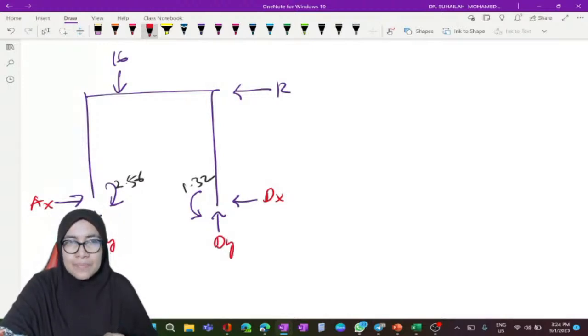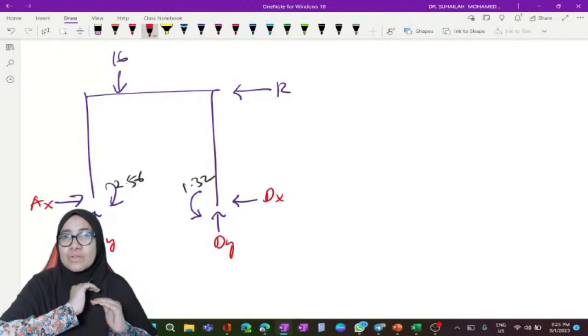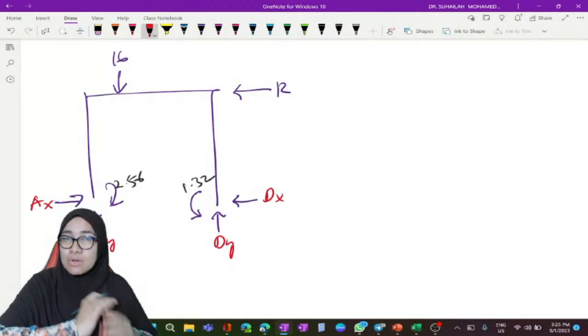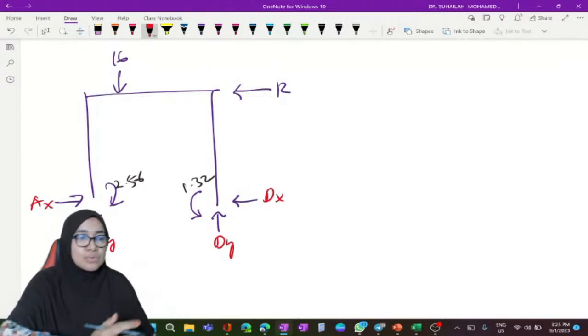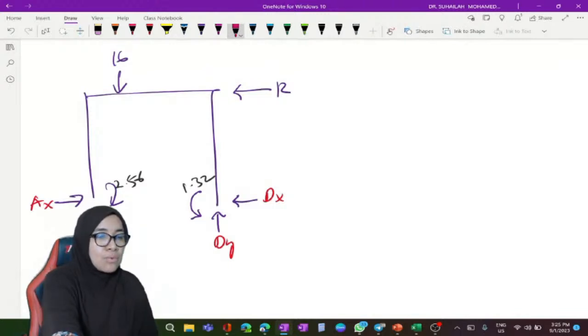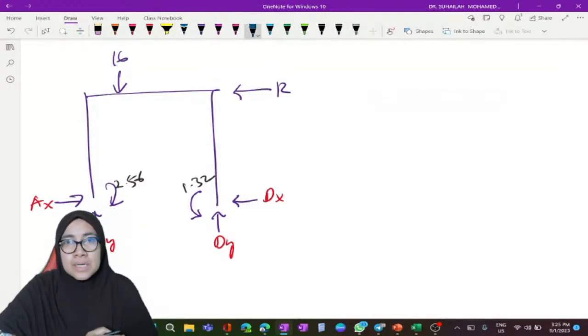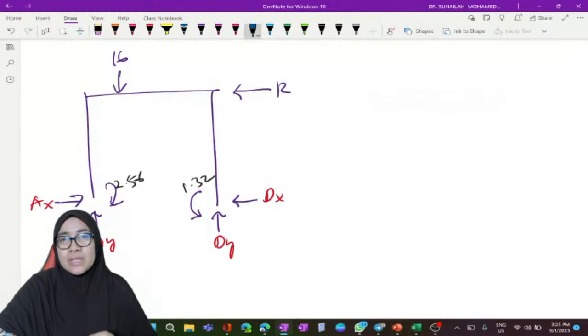Remember, at this level, we are analyzing this to determine the restraining force value. Restraining force in horizontal component is a horizontal reaction, which we get from the support that we put, the artificial support. So since we have to calculate R, we have to have the equation with which we can relate R. So we have to have what we call the shear equation, because we are referring to the column.